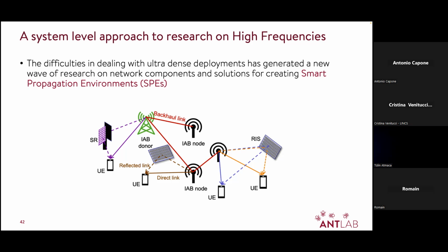Because smart repeaters for a technology like 5G, a repeater is an amplify-and-forward stuff, physical layer, right? But these are smart because they are based on MIMO. So they have a MIMO antenna on one side and another MIMO antenna on the other side, which is remotely controlled. So that's the reason why they are called also network controlled repeater. So you have a control plane for controlling the configuration of the antennas of the repeater, okay, which is analog, right? So it's analog beamforming, nothing to do with digital beamforming.